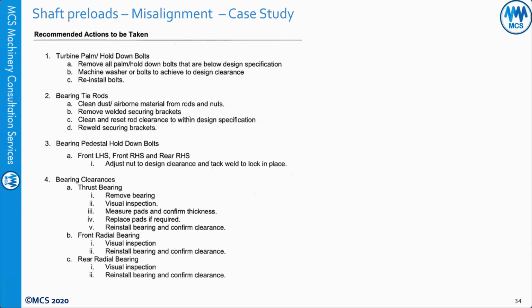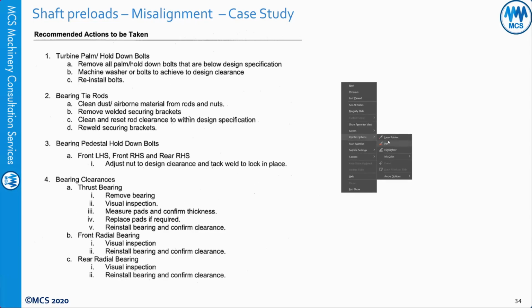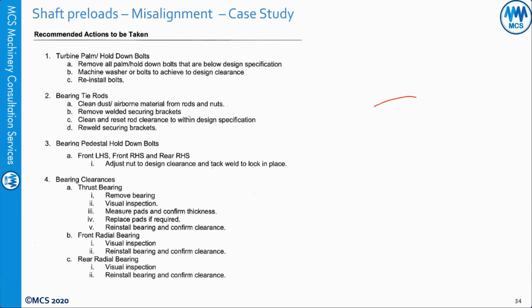So the thing is, we need to learn from this second case: you need to be careful about the difference in the vibration reading from the bearing cap and the relative displacement. Now, we need to talk about why the bearing cap vibration is high with low vibration on the relative displacement probe. Like, for example, this is your journal bearing and your shaft is here, and you have two probes. Okay, so the shaft is rotating here.